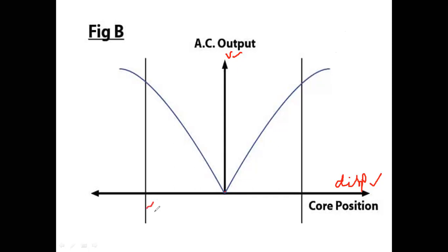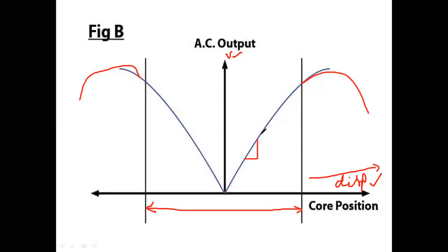So this is the range of the instrument for which I am using this instrument. Beyond that range, if I use the instrument, it shows non-linearities, means it will show error values. See here, within the instrument working range, the sensitivity, the slope at every point, is the same. Since sensitivity is the same, the instrument has high linearity. Okay. We always want to make the system linear.